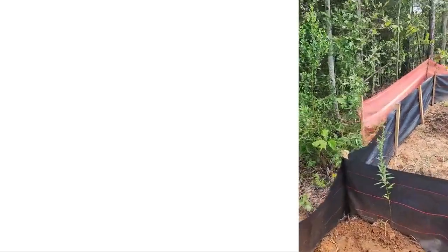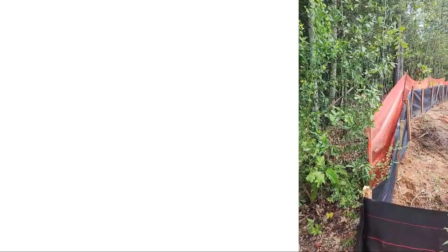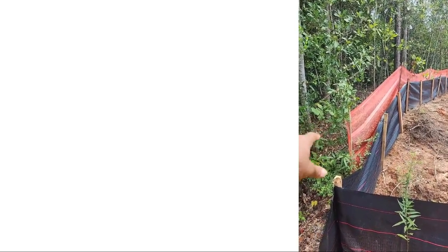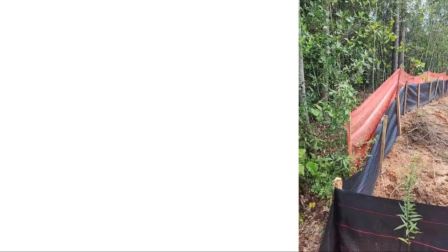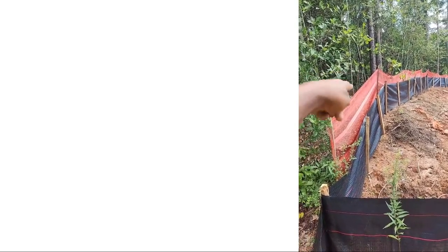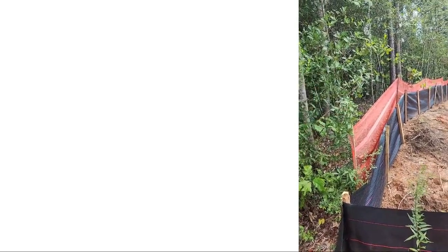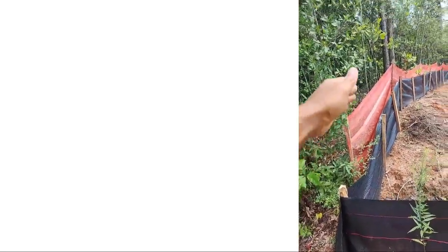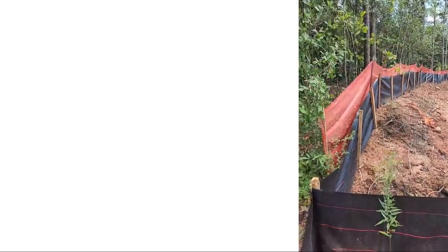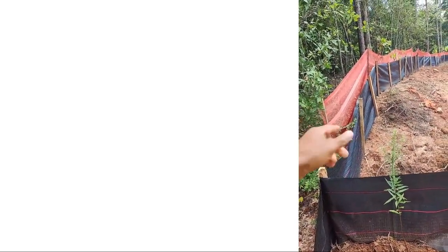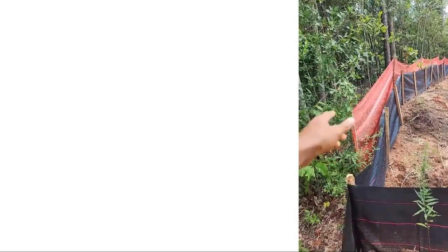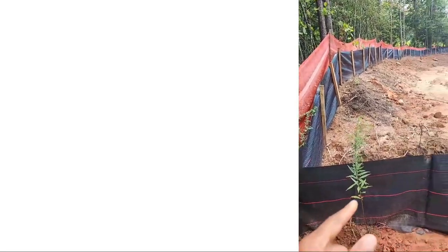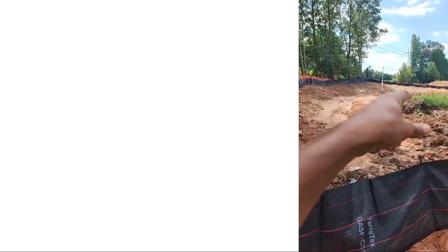Now, according to our plans, we have to have a tree save. Okay. So the tree save is the orange one. The orange one doesn't have to be buried deep. It's just something that covers and protects the tree, the root areas of the tree. It goes all around behind the silt fence. The silt fence is to cover the erosion. The tree save is to protect the root areas of the tree so that we don't disturb it. And all our work will be done within the silt fence area.